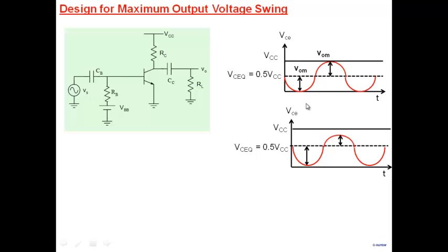All right. So this is something that we had seen earlier. This is the picture that we had earlier, right? A perfect sinusoid, which gave us that bias in the middle, VCC by 2, to get a maximum swing. The picture that we are seeing now is more like this here. The positive swing that you see here is much smaller than the negative swing. It's a distorted sinusoid. So the picture is quite different. It's not a symmetrical sinusoid. This is more like the sinusoid that I get when I apply an input here because of distortion.